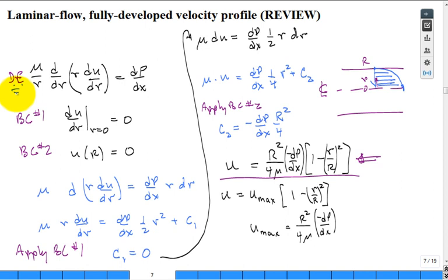This is great. All right, so this is our momentum, linear momentum balance equation. It's our F equal MA. So what's this? This is the F pushing it down the pipe. Is it accelerating when it's fully developed? No, it's just going on. So the linear momentum isn't increasing or decreasing. But what is this then? Well, that's resisting it. So you have competing pressure pushing it down, and you have the viscous effects holding it back. Well, this is a differential form.